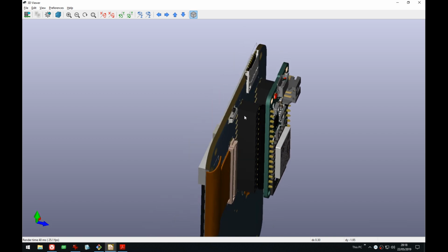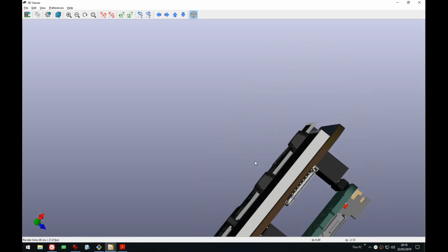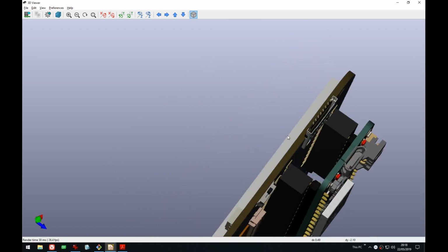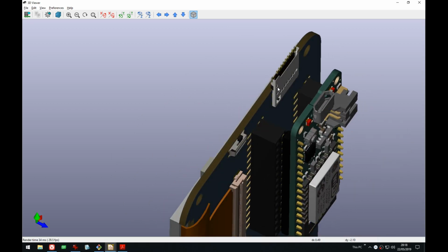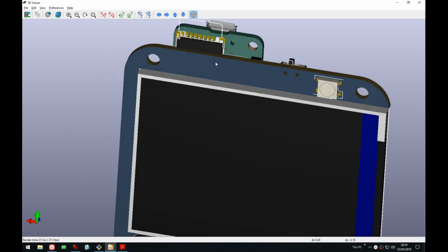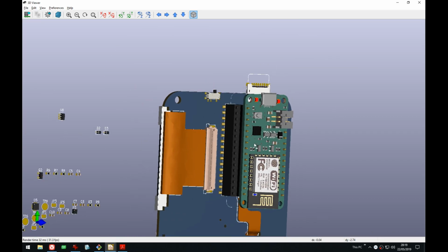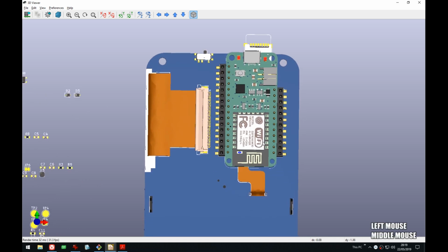But even if these female connectors here are half height, you still get this standoff on the male side, or you could remove it. You could do some tricks here to get as low profile as possible, but I think pretty much no trick will make it so thin that it would actually have a problem with the micro SD. So I think it might make sense to actually have it there. I don't see why that wouldn't work.